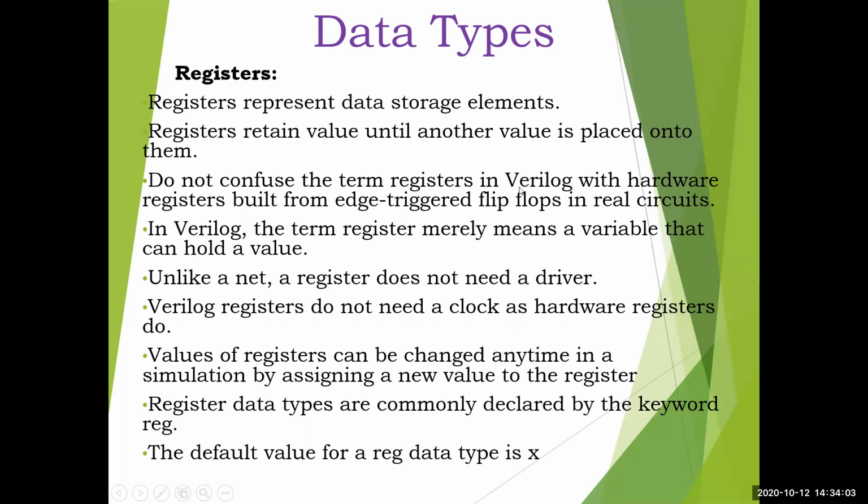Do not confuse the term registers in Verilog with hardware registers built from edge-triggered flip-flops in real circuits. Actually in microprocessor kits, we will be having registers like serial in parallel out, serial in serial out, parallel in parallel out, parallel in serial out, different shift registers. This is not that register. So do not confuse with that.